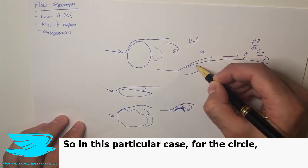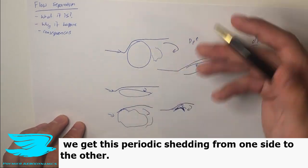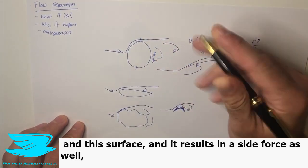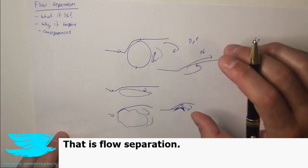In this particular case, for the circle, we get this periodic shedding from one side to the other, and that results in this fluctuation in pressure on this surface, and then it results in a side force as well, which can rock this geometry and even break it at times. So that is flow separation.